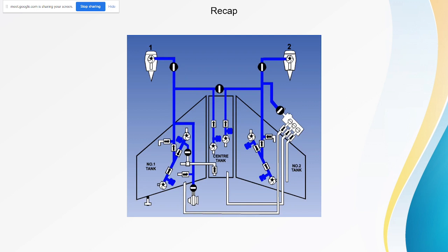In this system, we have fuel tanks, which are main wing tanks number 1 and number 2, and also the center tank, which are interconnected to each other and to the engine through the lines and fittings. Next, we have valves along the line that are used to control the direction of the flow and also to stop the flow. When the valve is in the cross position or perpendicular position, the flow at that particular line will stop.